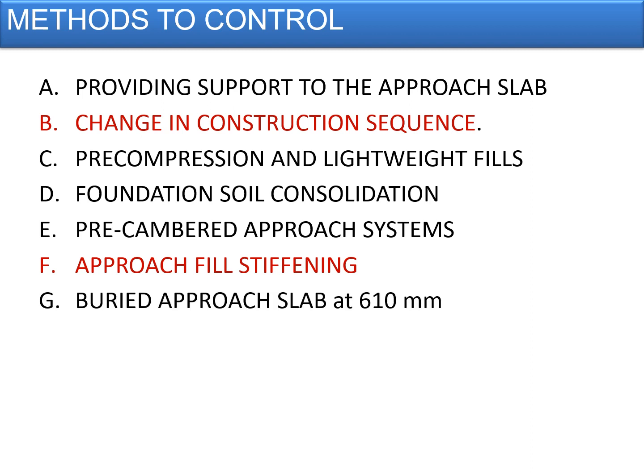In the current module, we will be discussing in detail the buried approach slab at 24 inches below the deck level or 610 millimeters below the slab top, and the provision of preformed grout holes in order to control the settlement of the approach slabs.